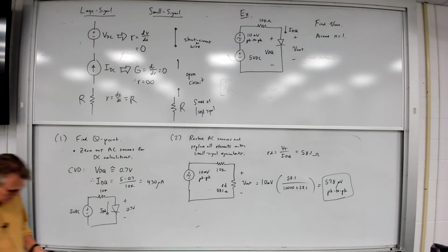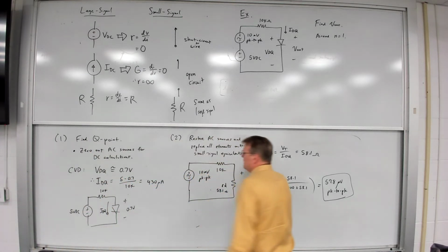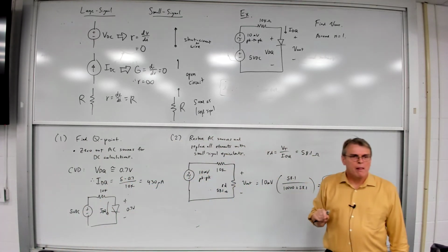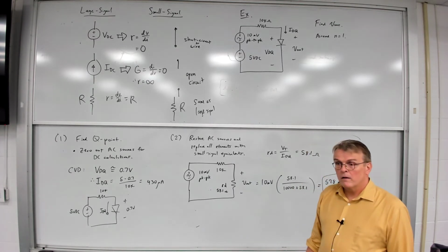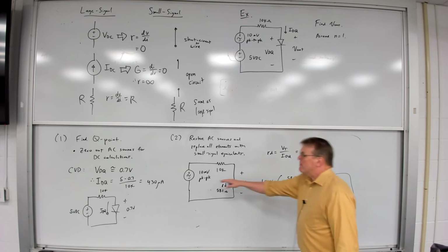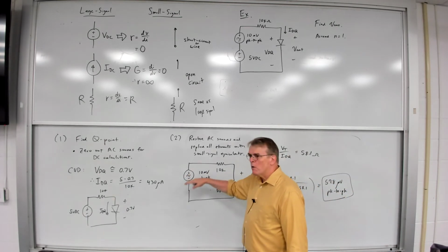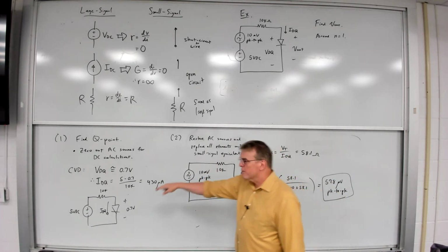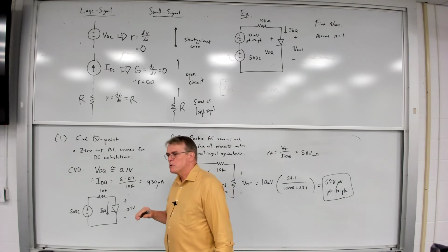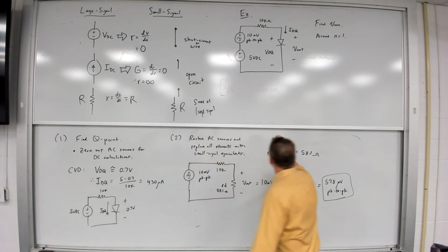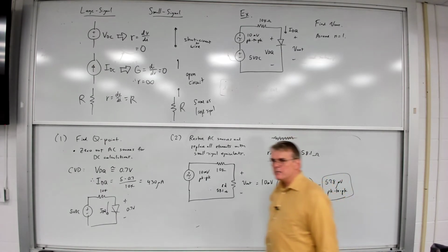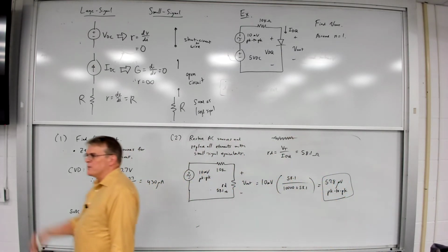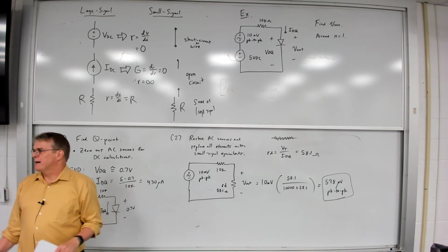All right? Now, questions about this? Yeah? So is this 10 millivolts going about the Q point? Well, yeah, probably yes. What we're saying is the AC voltage will be superimposed over the DC voltage values. So think about it: here is some DC value, and we'll have some small AC value riding on top of that DC component. But in the small signal analysis, we just ignore the DC, right? It zeroes out.